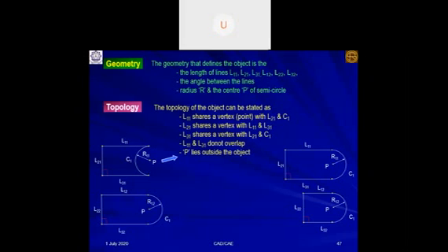So in solid modeling, modern CAD systems offer two approaches to create the solid model. One is the primitive based approach, another one is the feature based approach. In the primitive based approach, it allows the designer to use predefined shapes like primitives as building blocks to model a solid object. It is similar to, say, if you would like to build your house, your building block is the bricks, small bricks, you just add them by mortar.